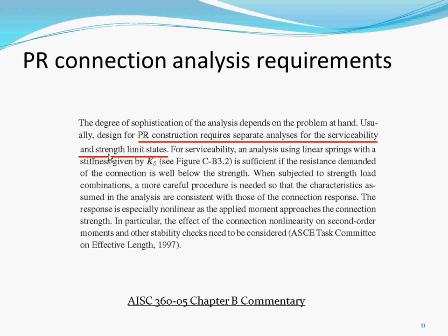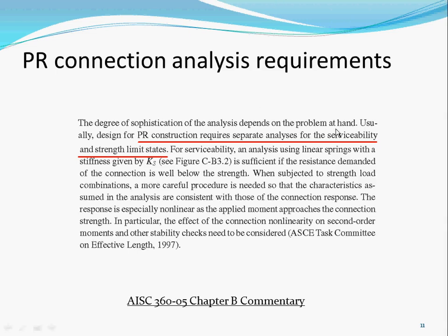Deflection and even drift, they consider that serviceability. For strength, it's: how much strength do I need, like moment, shear, and axial? Can my connection take all the load from these cases? So you need a separate analysis for the serviceability and the strength limit state.